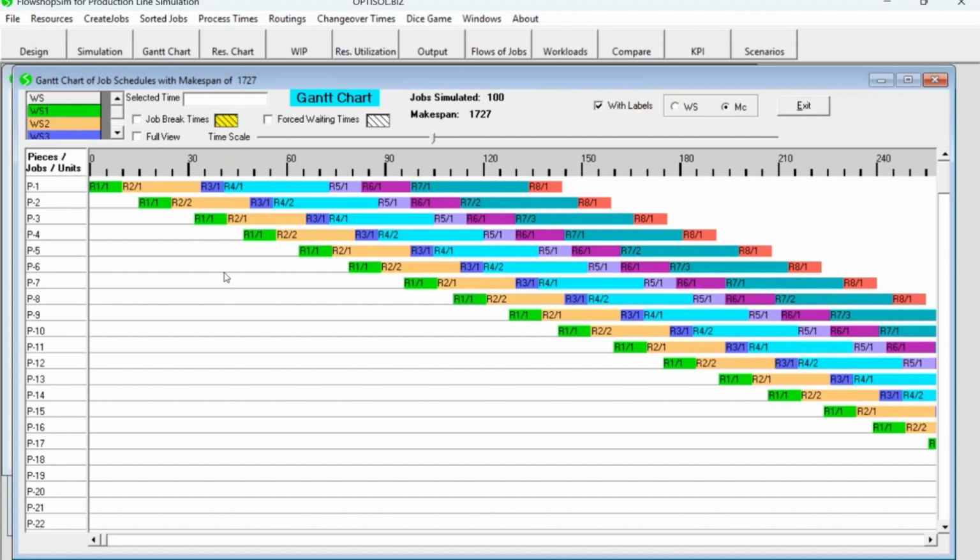Let us look at the workflow. You could see here, each piece is released at the right time to the first work center so that that piece does not wait anywhere. So note that the cycle times are different, the number of machines varying with work center. In spite of that, we can release every piece at the right time so that the piece does not wait anywhere. This is one-piece flow in this unbalanced line. But I cannot do that if there is any random variation. So this is the second scenario.